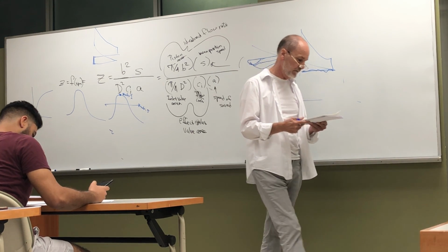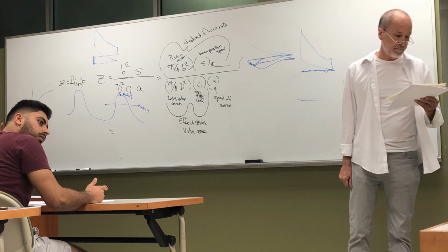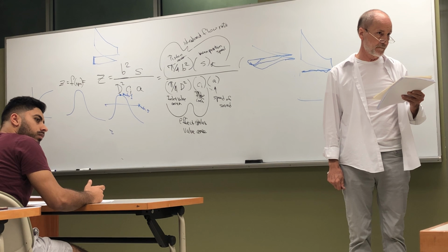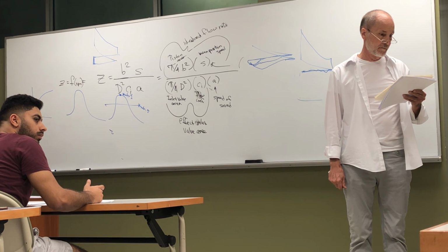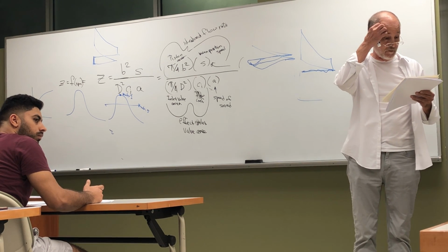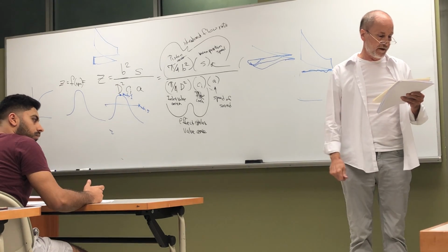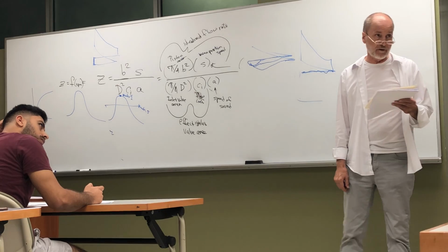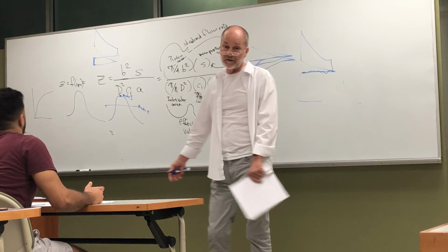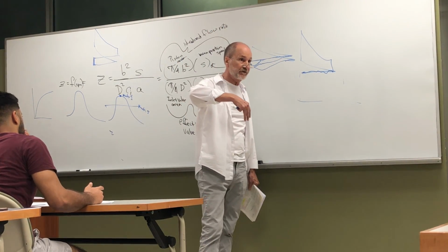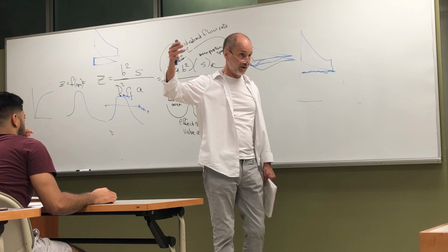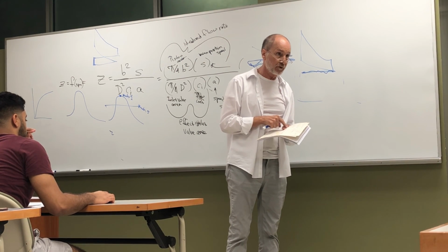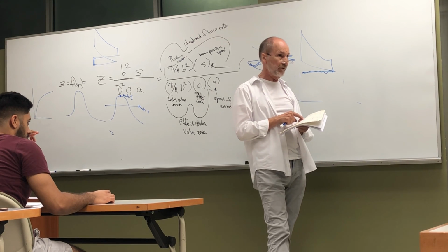Okay. Yeah, so we're losing the volumetric efficiency. If I wanted to get that pressure up, would there be any benefit to blipping the exhaust valve open really quick to bring the pressure up, if you were able to do it? In which one? The bottom left one? Well, all you're going to do, if you've got low pressure in the cylinder, is open the exhaust valve. At this point, we absolutely want the pressure low, because we're at low power output. Remember, we don't have our foot on the gas.